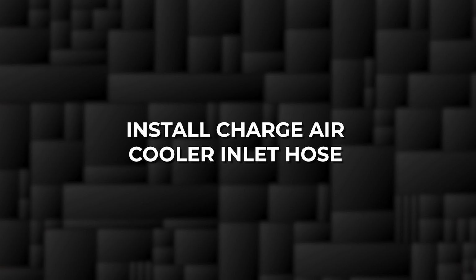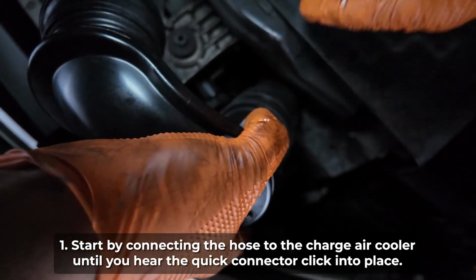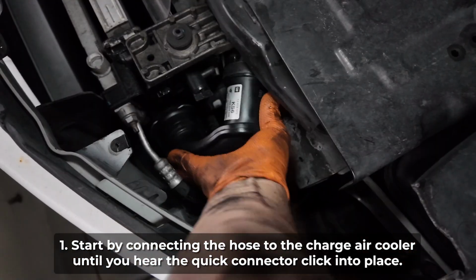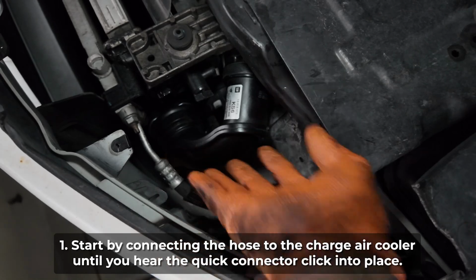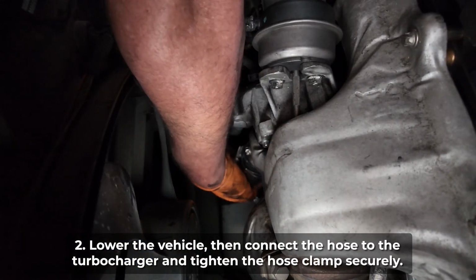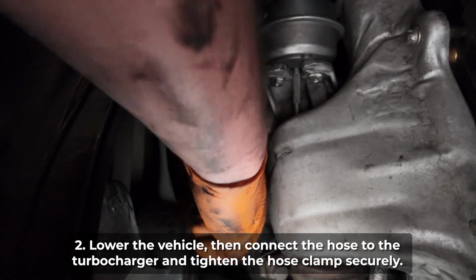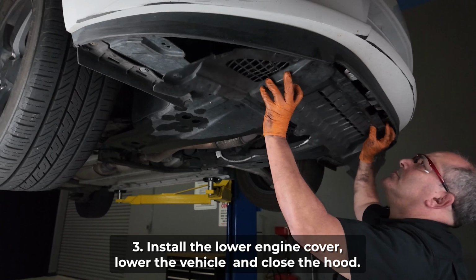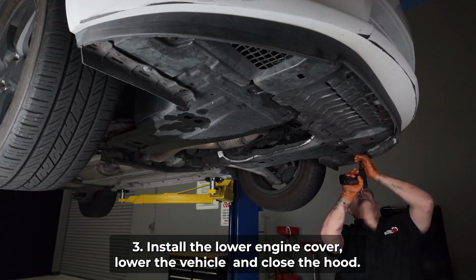Next, install the new charge air cooler inlet hose, the hot side intercooler hose. Start by connecting the hose to the charge air cooler until you hear the quick connector click into place. Lower the vehicle, then connect the hose to the turbocharger and tighten the hose clamp securely. 3. Install the lower engine cover, lower the vehicle and close the hood.